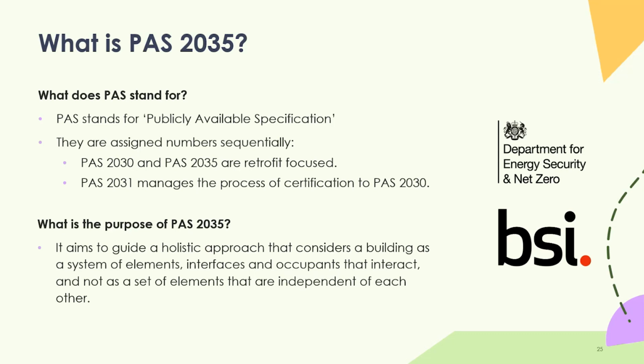disaster in Preston, where you had hundreds of EWI jobs done on homes. They were done really poorly without any proper thought for the moisture management, basically, and it just destroyed the fabric of loads of buildings. It was quite a scandal, especially when the company then went out of business and disappeared. They're still spending money cleaning up the after effects of that. The NEA has done a lot of work with that particular scheme to repair things, so I'd really recommend looking into that if you're new to retrofit. That prompted this Decent Homes review, as it was called, which reviewed the disaster and effectively then led to the creation of PAS 2035.